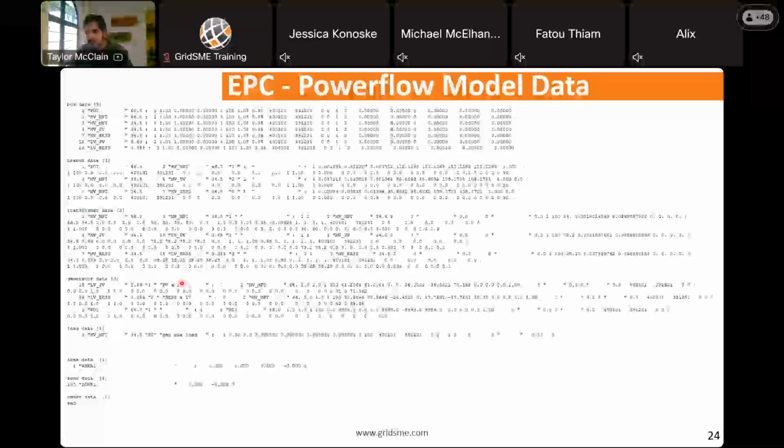As you can see, there are 17 PV inverters and 17 BESS inverters, but we only have one PV pad mount and one BESS pad mount, and one PV generator and one BESS generator. And then up here, one PV collector and one BESS collector. So you can see that the equivalent modeling approach has been utilized here.